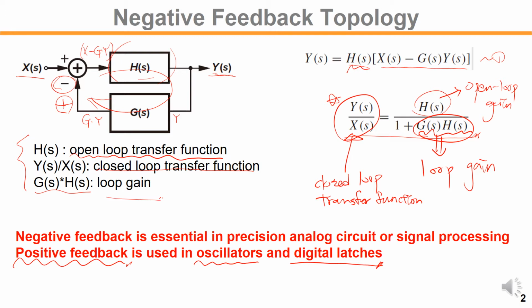One thing that we have already seen is that one of the differential loads has the cross-coupled pair like this. This is a typical positive feedback. Why? Let's say the drain voltage on one side goes up, then the current increases in the right transistor, so the output drain will go down.